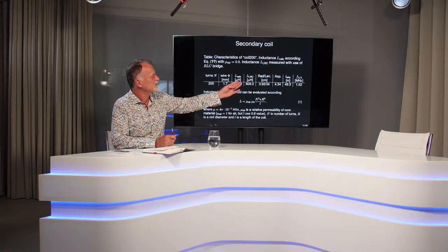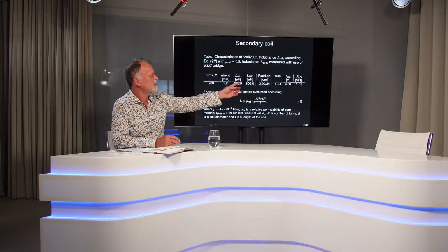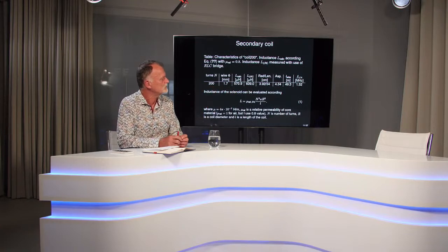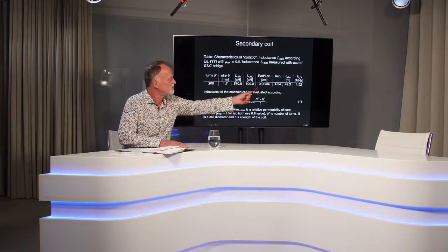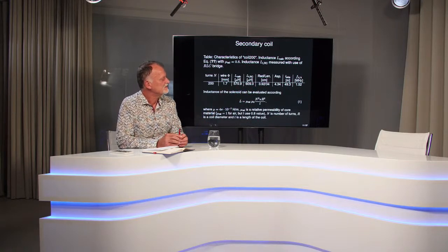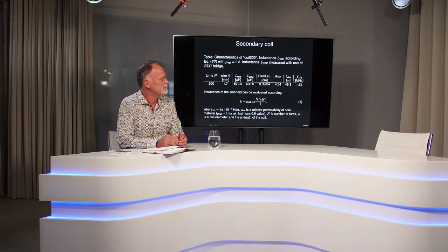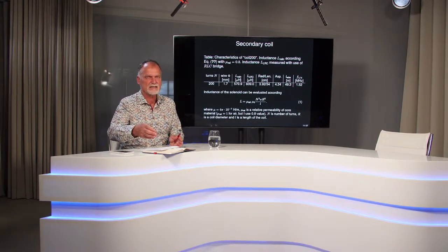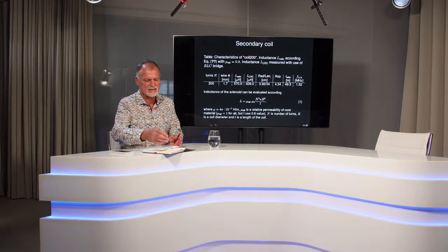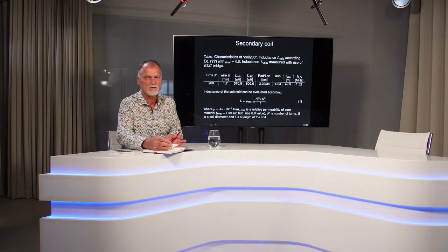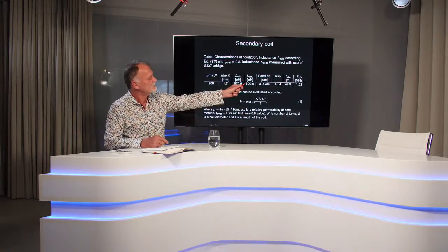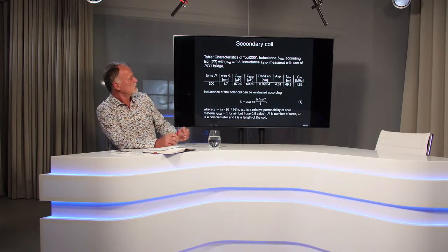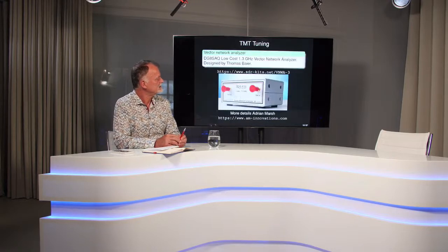Then the important thing is that the coil should have an aspect ratio, meaning the length and the diameter should be close to 5. In this case we have 4.3. That's fine. The wire length is 50 meters. It means lambda/4, so in order to have the maximum voltage at the hot end, you have to set it up such that it acts like a lambda/4 antenna. And this lambda/4 frequency, in this case, is 1.5 megahertz, right? So we can go to the next slide, please.